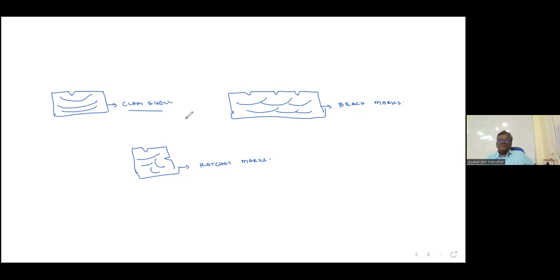Fractured surface, only we can see the marks. Okay. Now, coming finally to how to prevent it. So I told you design, or we can go for heat treatment also, to improve the grain size. Then which NDT will detect it? Because here there is no corrosion, we can do PT also. We can do PT, MT, but if it is happening inside, we can use UT also. Okay, so please take note.